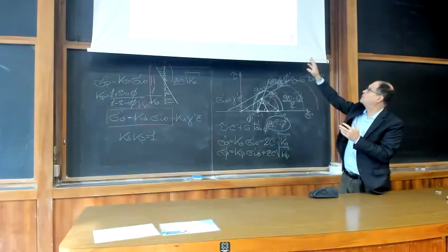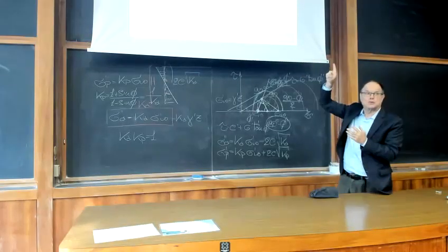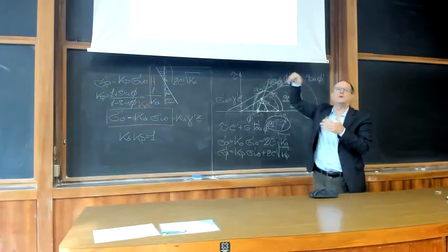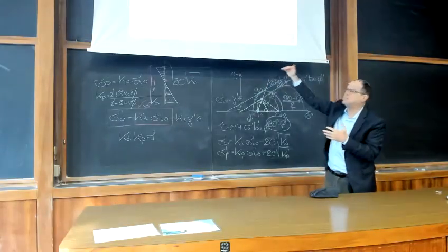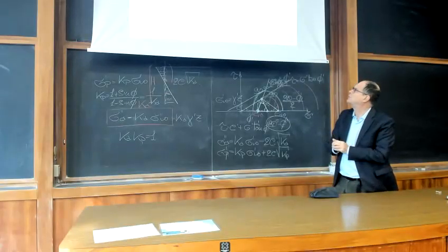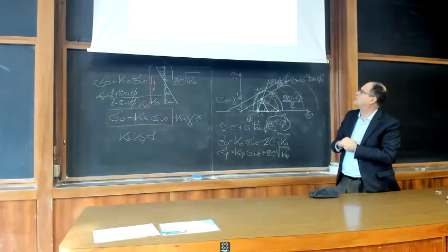And most of the time you design your pile according to that shaft resistance. You can neglect the tip resistance, or you will use it, as you will see when we go into the details of the design of a pile.